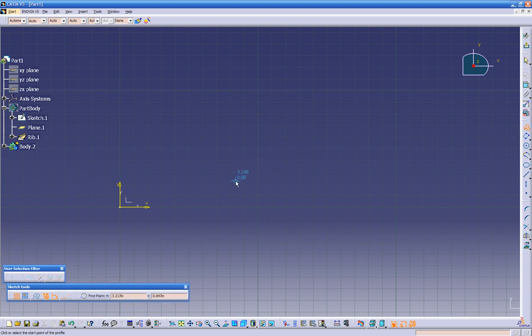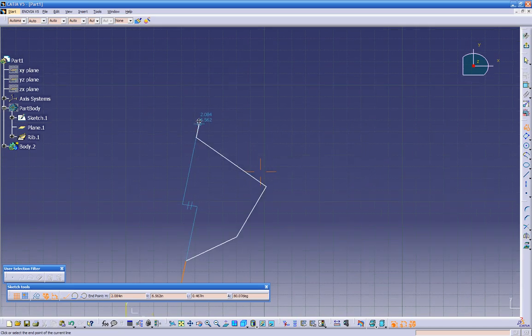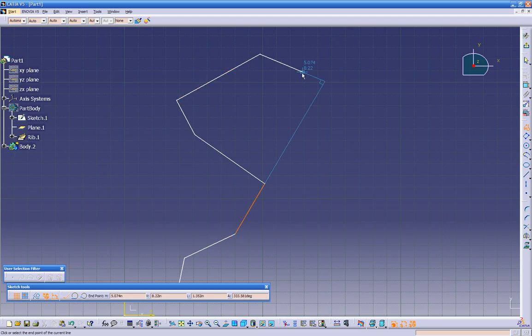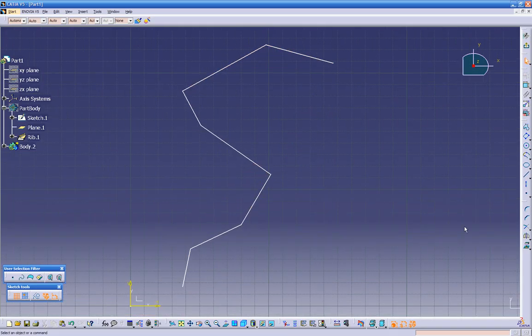Let's create again a shape. We're not gonna put corner radius this time because, click escape, we want to try the corner radius option again. So click, if you double click, we'll just stay active. So you can put the radius over here. We can put a corner radius over here.